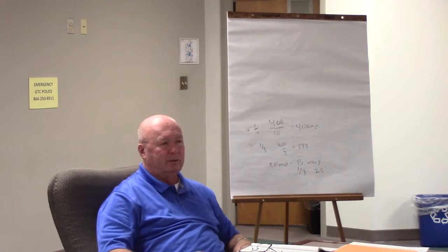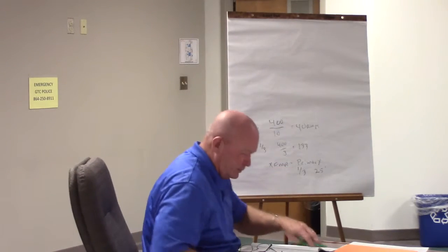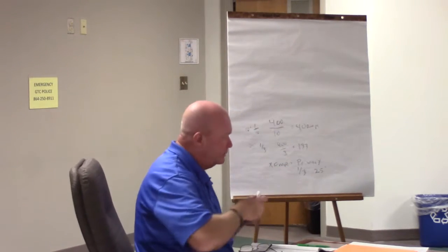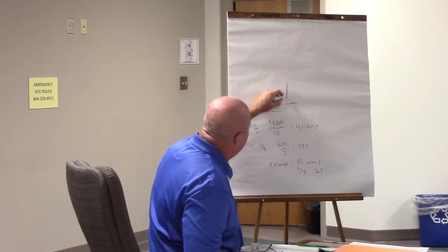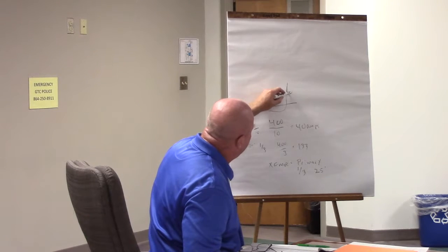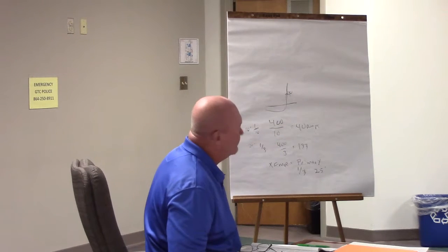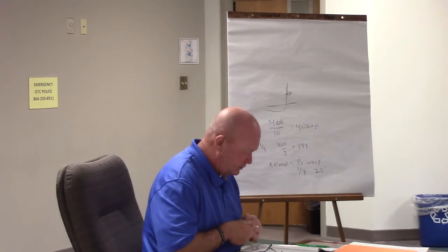Okay. So, come in through the wall. I know it's easy to say. Coming through the wall, you're outside, you're coming up, you come through the wall, you better have that disconnecting means right there. Okay. Right there's penetrate the wall. That's what that's saying. And it makes sense.